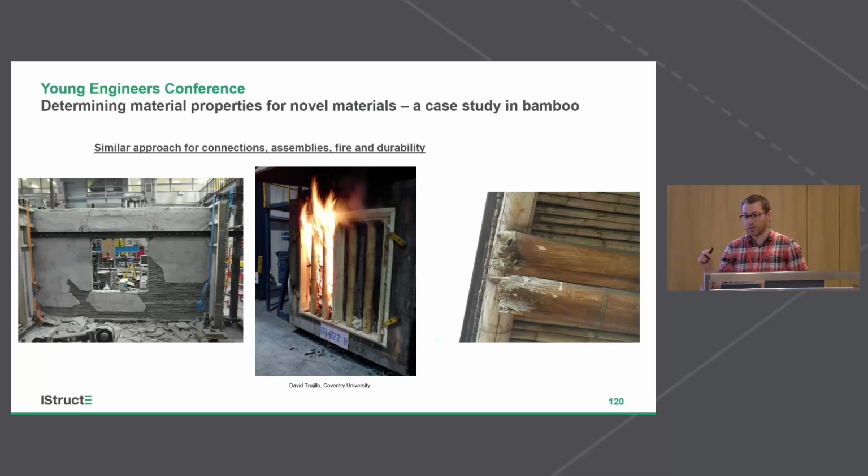The penalisation applies equally to something like that. So that can be a bit of an issue, but it means that we need to be much more careful about the testing that we do. We need to think even more about exactly what testing we need. But equally, on an assembly, we shouldn't just necessarily test the entire system. It's possible that we can determine some failure modes from first principles using engineering judgment or test them separately.